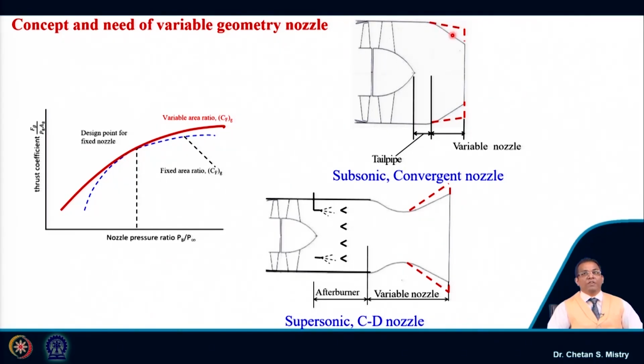Suppose I want to extend my operating range for a fixed convergent nozzle; I can incorporate a variable area configuration with which we can change the exit area. In line with that, for a convergent-divergent nozzle, in the same way we can vary the exit area. Nowadays people are talking about varying the throat area, which is also one kind of option.